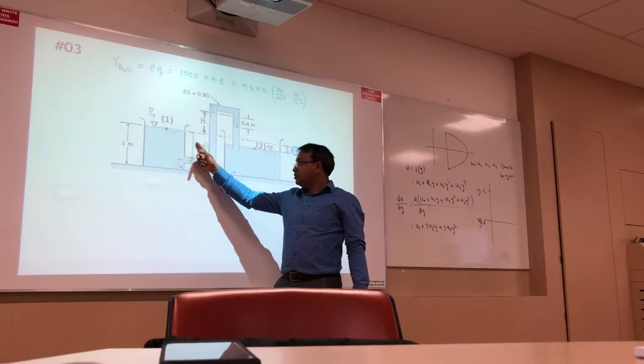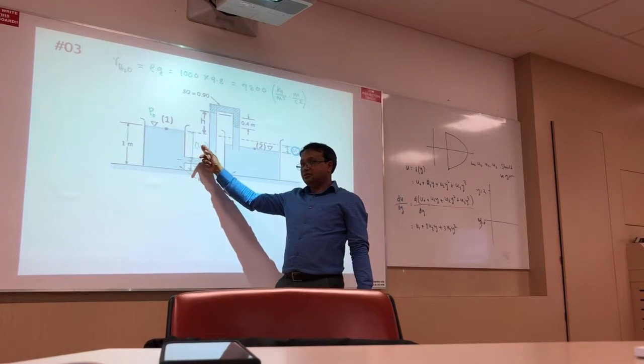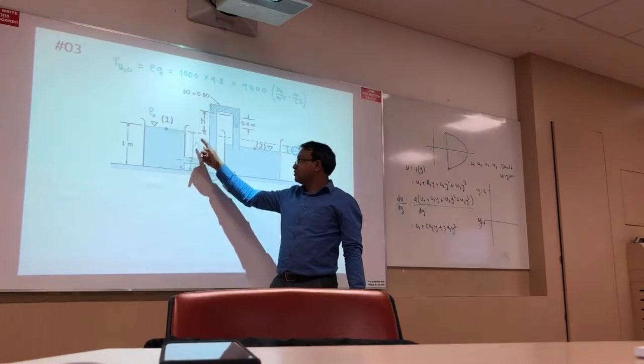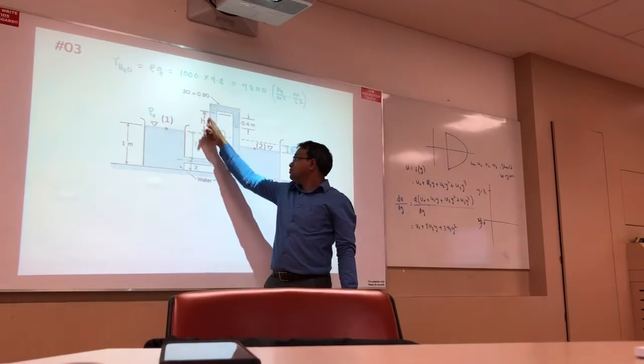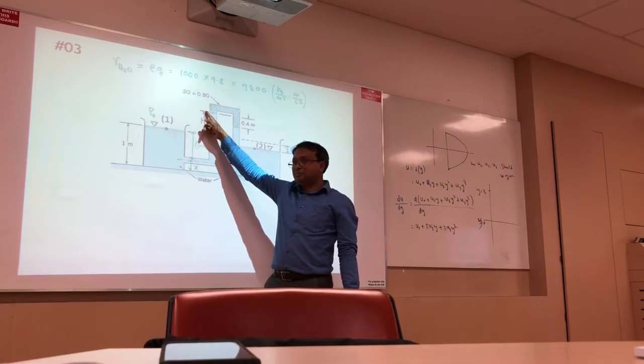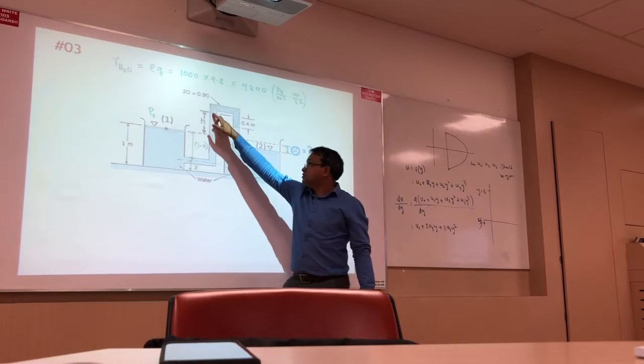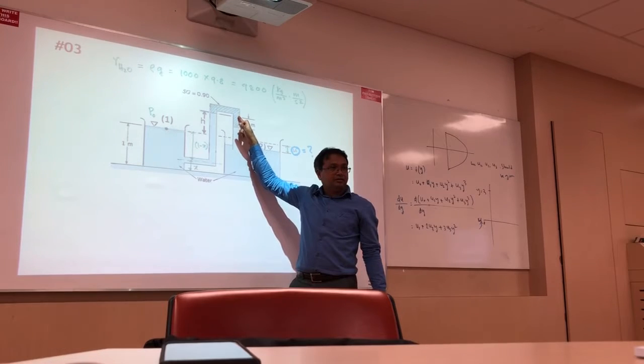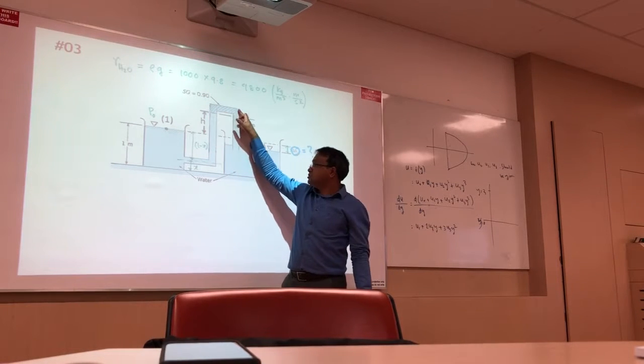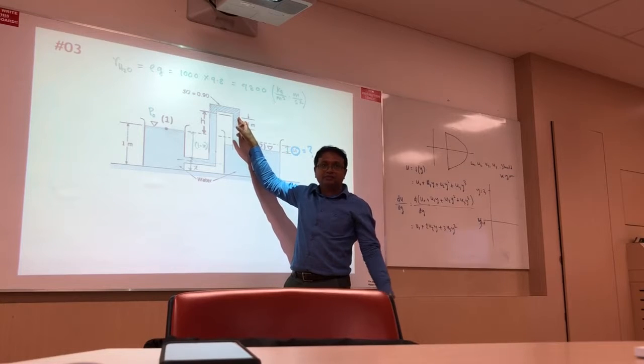From here, rho G times 1 minus x. From here to here, same fluid, rho g times h. This distance and this distance are the same, right? And we can cancel each other. Same fluid, neglect. But different fluid, no, you have to consider.